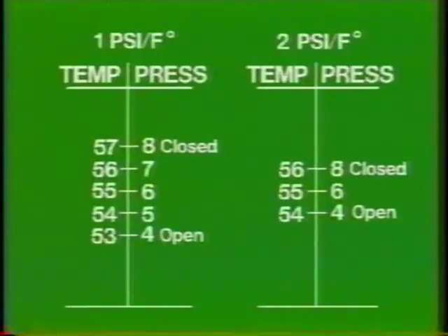That would be 0.12 times 16, or approximately 2 psi per degree. Now we divide the spring range by this new system sensitivity to get 4 pounds divided by 2 degrees, or a throttling range of 2 degrees. As in any proportional control system, we would attempt to achieve the highest sensitivity possible without producing cycling in the system.